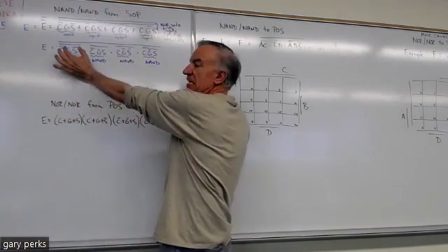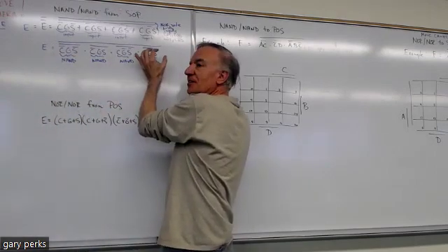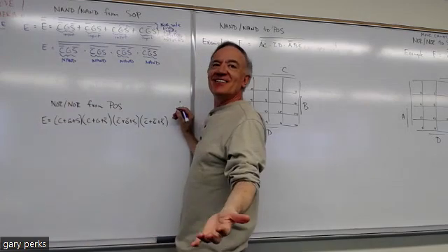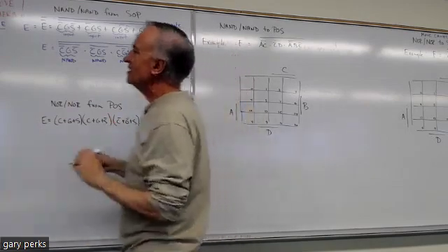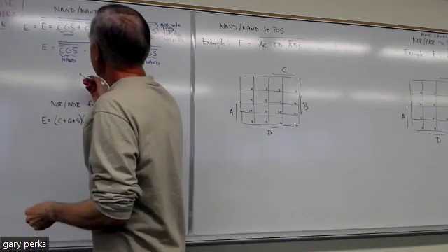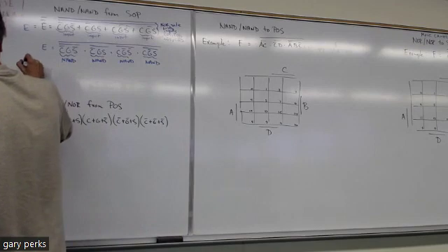And then we're taking each NAND, ANDing them together, and inverting the whole thing. So it's another NAND. See, that's why it's called NAND NAND, because unlike SOP and POS, where you got different gates, you got ANDs and then an OR, and here you got ORs and then an AND.